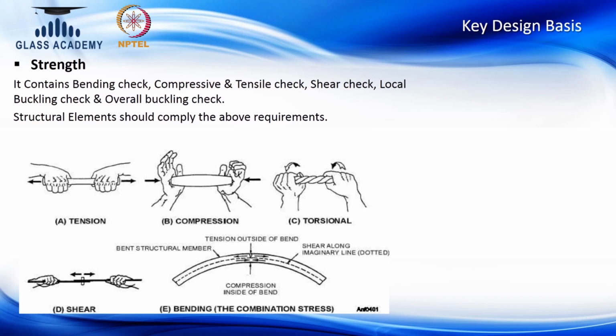And torsion in many cases is critical if the individual floor height is like 4 meters or 3.5 meters and it has a large span of unsupported length. And shear, primarily checking for fixing connections and brackets.